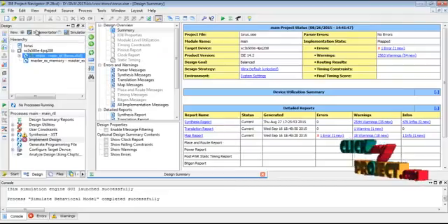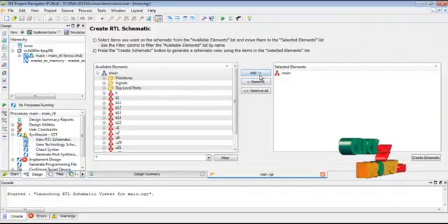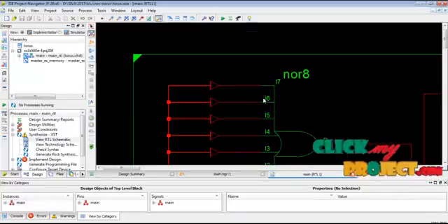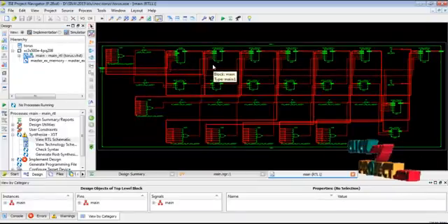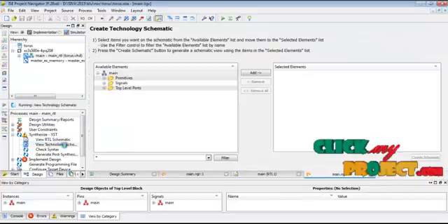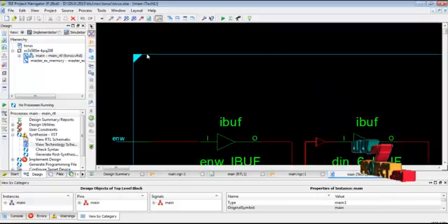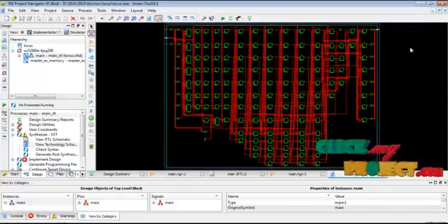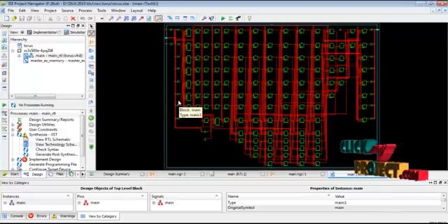Then we go to the implementation-based process. The implementation process identifies the RTL diagram. The RTL diagram represents the logical blocks present in our 3D-based NoC architecture design. This is our required logical diagram for the 3D NoC architecture design. Then we go to the technology diagram. The technology diagram represents the FPGA structure and method design-oriented process. This shows our lookup table and flip-flop pairs, input-output, and buffer element connections for our required